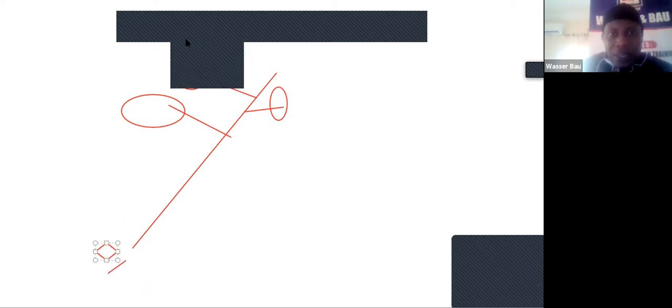This outfall means there must be a river here flowing. Normally you use riprap here to avoid the scouring. We do some scour protection there.